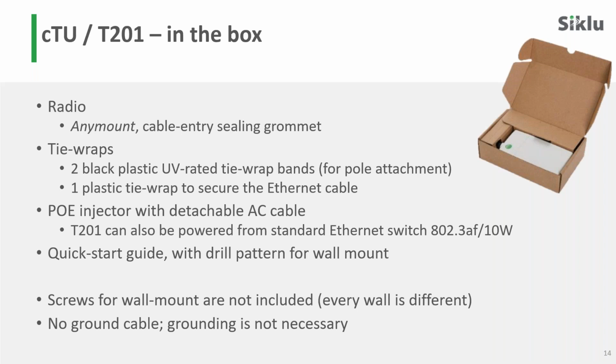However, because the T201 is a standard PoE PD device, according to 802.3af, if it connects to a switch which can provide power over Ethernet, basically if the switch is a PSE, then the T201 will do the proper negotiation with the switch so that the switch will provide power directly to the compact TU, and the PoE injector does not need to be installed.